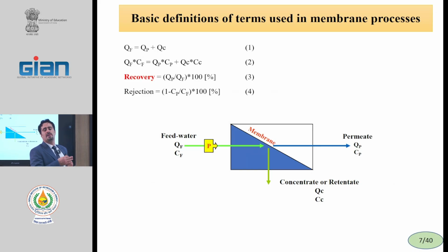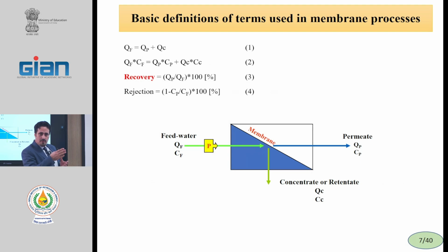We want to separate water from a solution and concentrate it: for concentration of milk, we want to reduce the water of milk; for concentration of dye, we want to concentrate the textile dye for reuse in dyeing. Therefore, related to the membrane process, the main product can be concentrate or permeate.